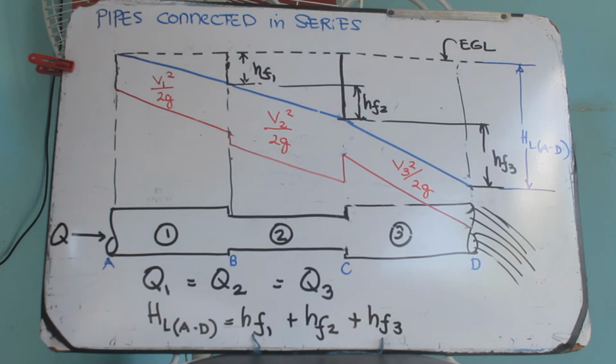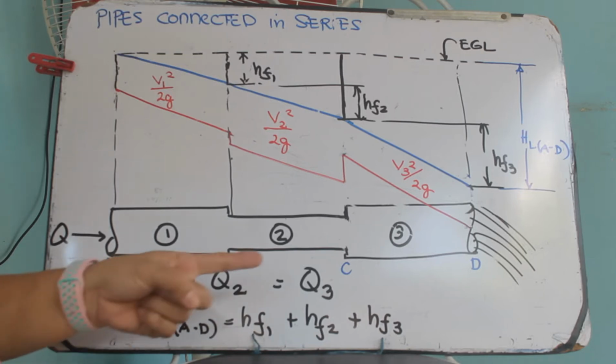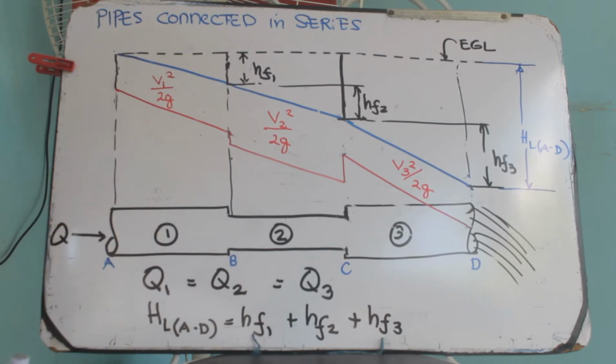Pipes that are connected in series, before we discuss branching pipes and pipes that connect reservoirs. Okay, so the figure here depicts the energy grade line and the hydraulic grade line. Reviewing, our energy gradients are always sloping downwards in the direction of flow.